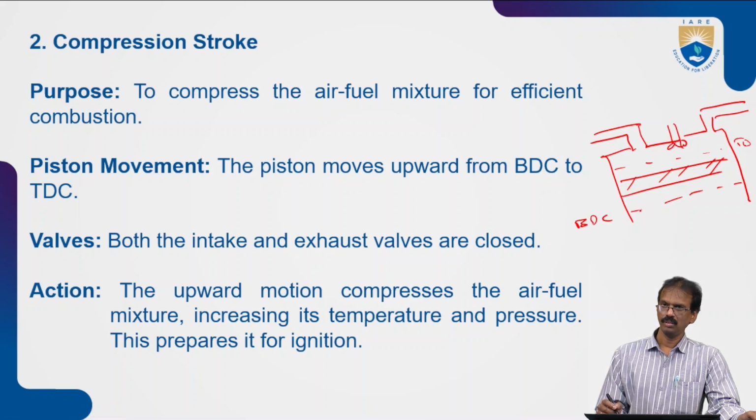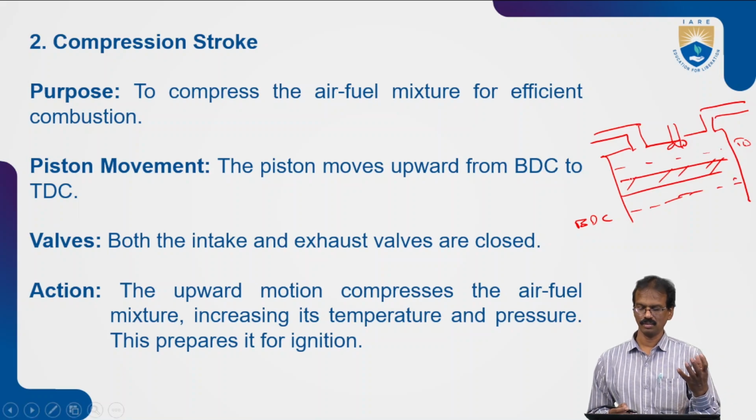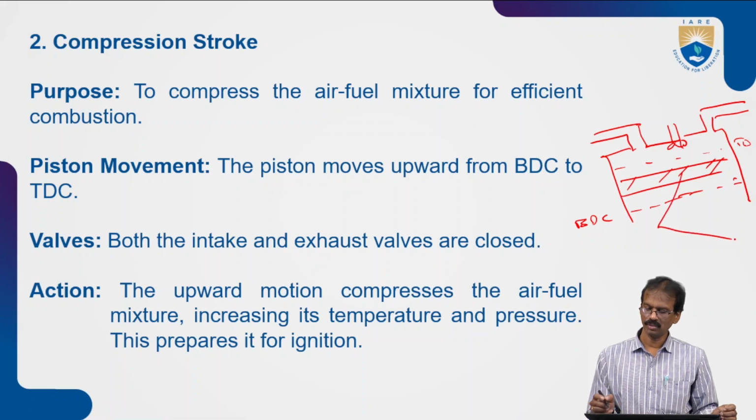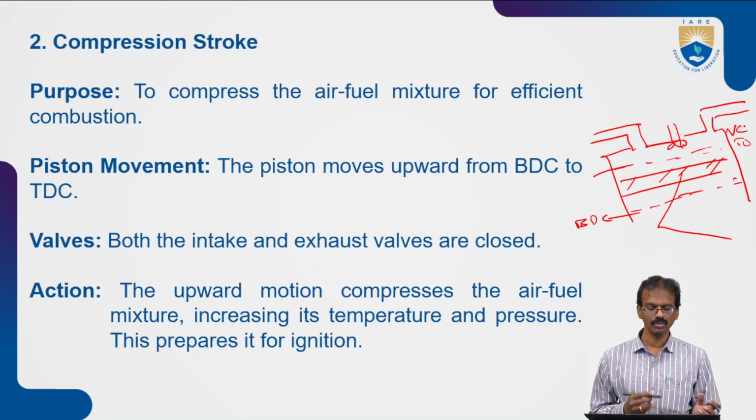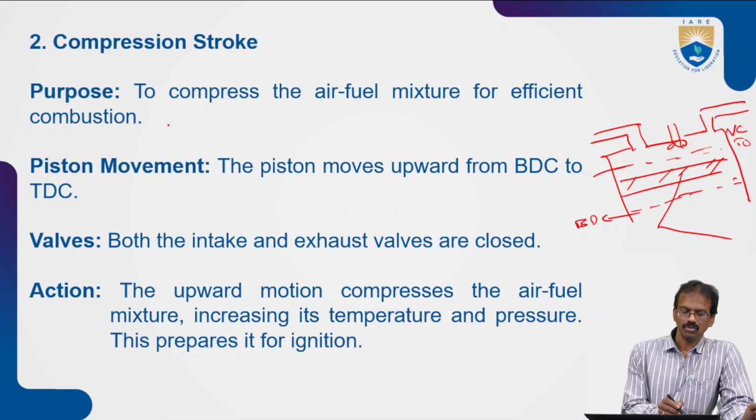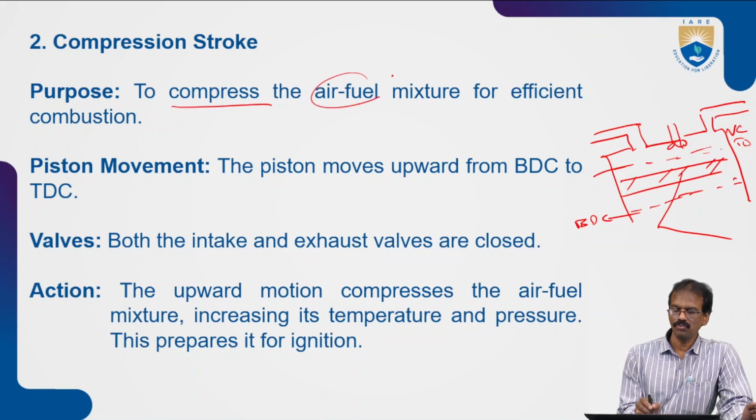In the suction stroke, the air fuel mixture is taken into the cylinder. In compression, the piston moves from the bottom dead center to the top dead center. In this, the air fuel mixture is compressed into the clearance volume. That is the compression. The purpose of this is to compress the air fuel mixture for efficient combustion.